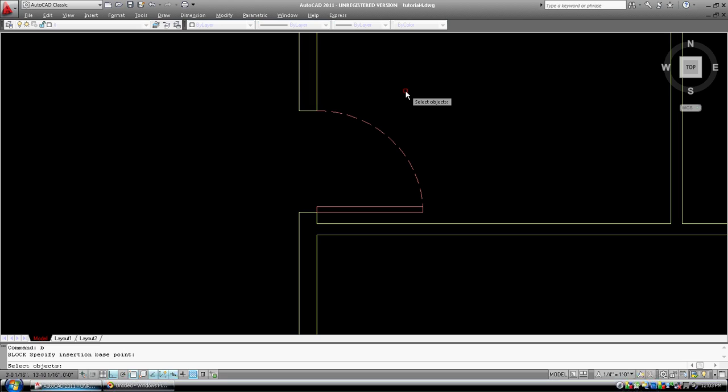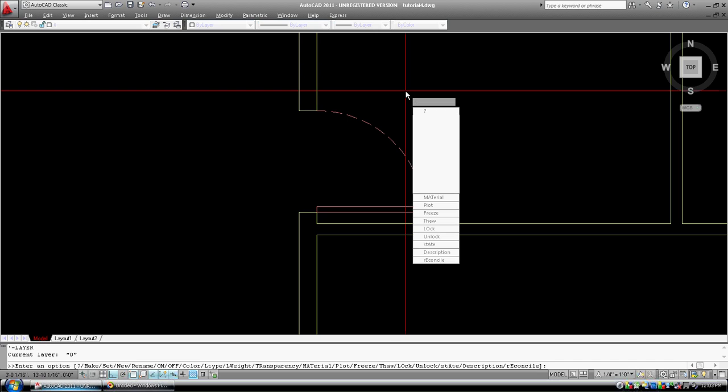It's a nice way of working with layers. So I'm right in the middle of the block command, and I want to be able to turn some layers off. So I use apostrophe. That breaks into the block command, and I figured out that to do layers on the command prompt I need to put a hyphen. So I put a hyphen, and then I get into LA for layers. Okay, and I press enter.